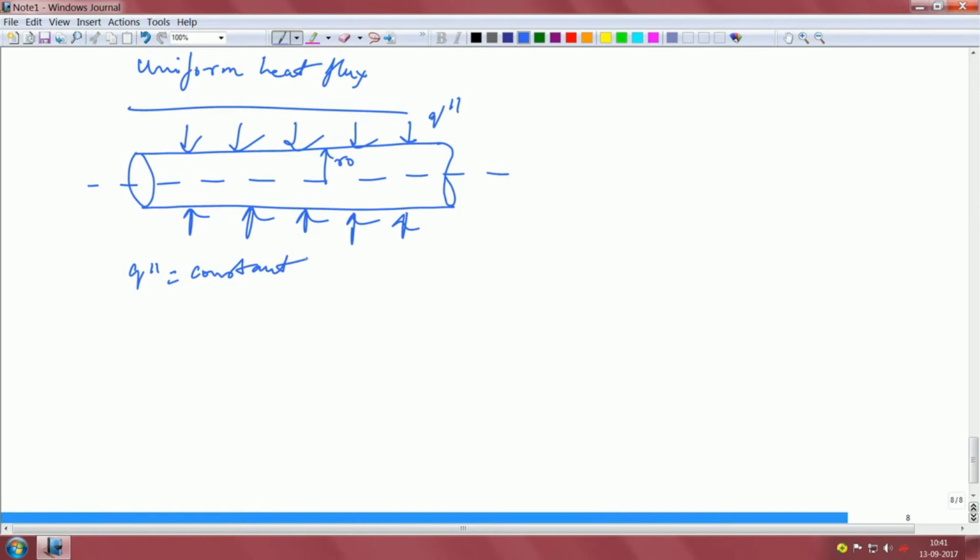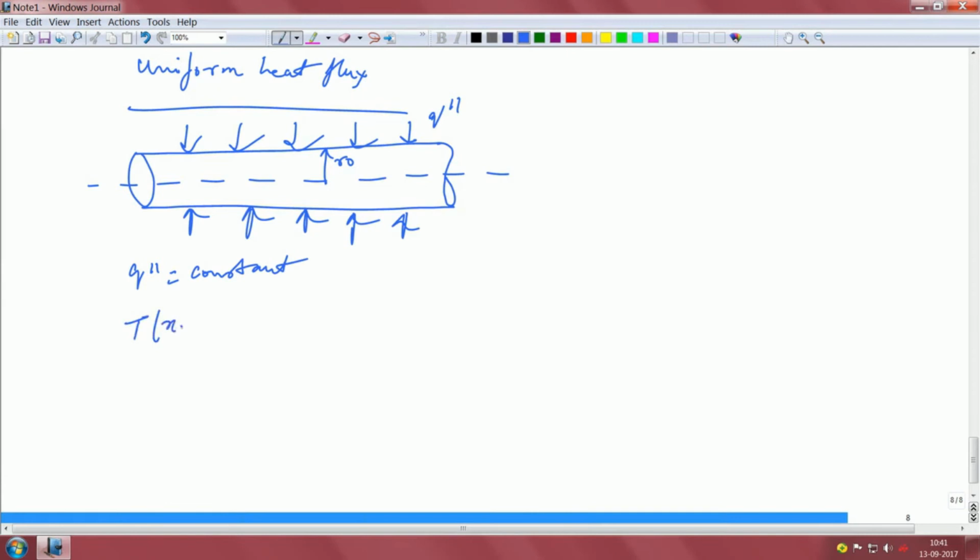Got it? So we have said nothing about the wall temperature. Here the wall temperature is not a constant. The wall temperature is still given by T naught, but it is not a constant, so we will see what that wall temperature is. So instead of defining the temperature in that way, let us first say T(x, r) equals T naught(x), and I am writing the functional variation so that you can get an idea, h f(r over R naught). That is the definition that we have applied.